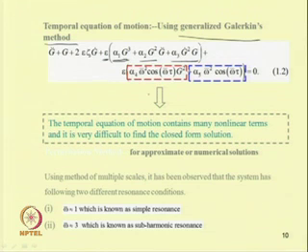here it may be noted that we have two more terms which represent the nonlinear parametric term. Here the coefficient of this G² is α₄ Ω² cos Ωt, which is a time varying term. Due to the presence of this term, the system becomes a parametrically excited system, and also due to the presence of this term, that is α₅ Ω² cos Ωt, the system is a combination of both forced and parametrically excited system.